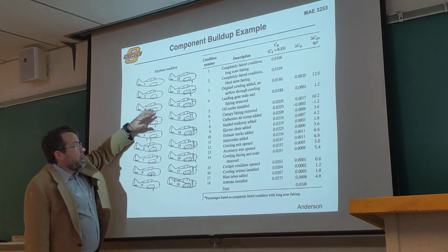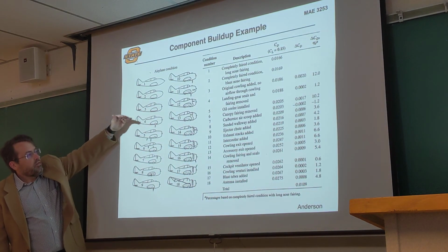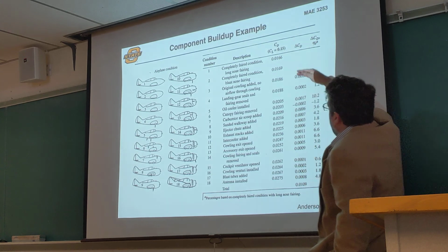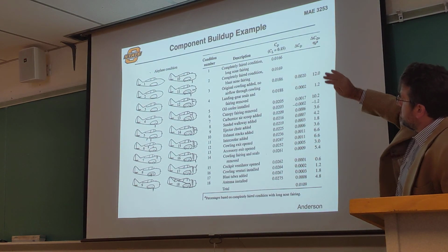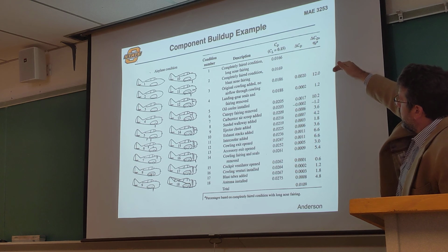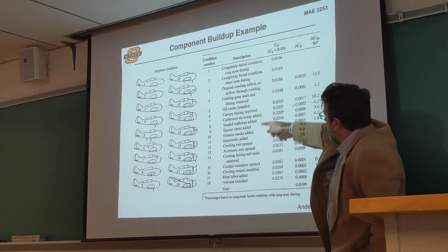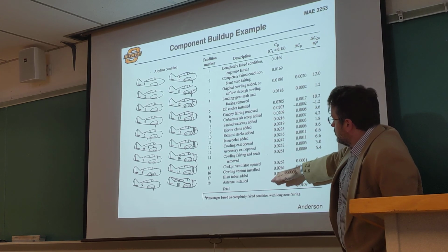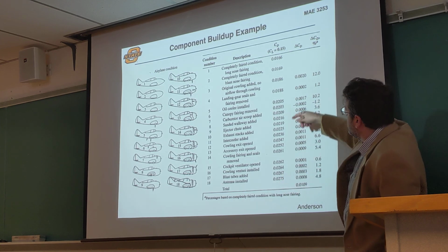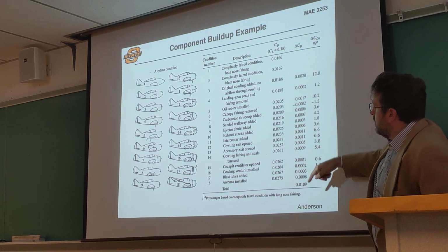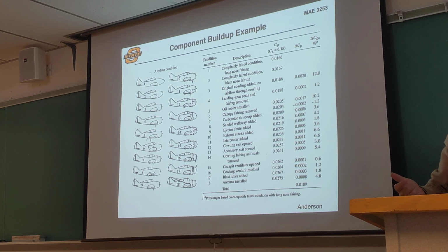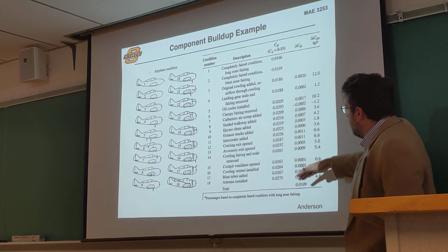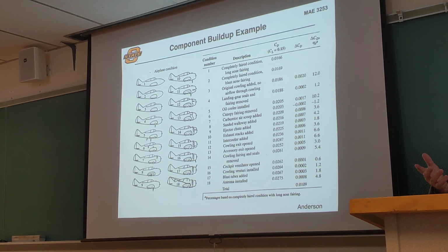So in this case, you're building it up and looking at the overall impact of adding each one of these components on. What's our overall drag? And this is looking at it in a slightly different perspective, where it says, well, what's our starting point that we have with our drag? And then when we start to do things in our aircraft, how does that change it? So this is basically our running drag value as we go through the process, and this is what our end-up drag becomes. And you can see how much we're adding each time we put an additional detail on to the aircraft. And each one of these by themselves is pretty small, right? But when you're adding all of them up together, you'll notice that becomes fairly substantial.